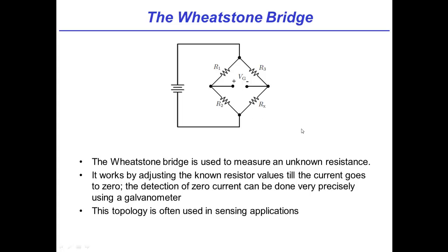So I'm sure you're going to work through the math in a minute, but I guess where this would be useful is if there was a sensor that changes resistance as a function of something I'm measuring, like maybe temperature or mechanical deformation. And what you're saying is a really good way of measuring how that thing is changing is to embed it in this bigger circuit with these 3 other resistors and measure this little VG maybe.